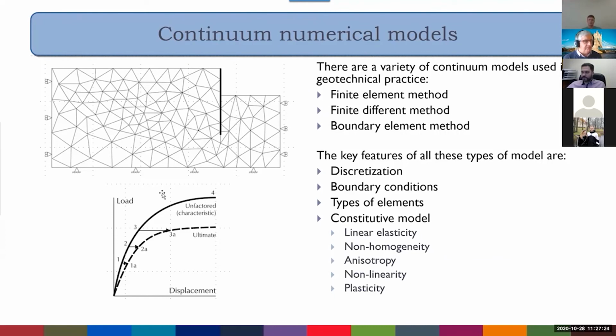You need to have a lot of knowledge about the stiffness of the ground, the strength of the ground, the stratification. It's a bigger buy-in to do the calculation. If you have a simple model and you have the wrong parameters, this will give you the wrong answers. So it is better if you've got the data. It's probably overkill on simple retaining walls because you just can't justify the time spent doing the more sophisticated calculation.